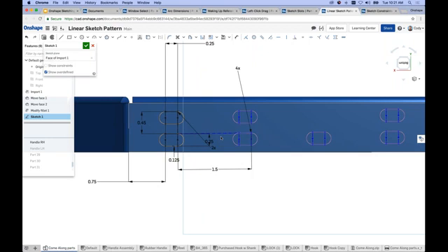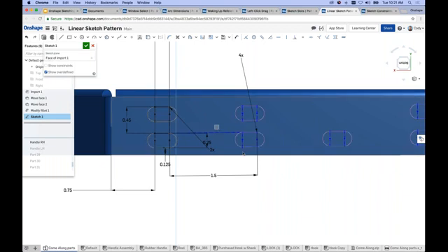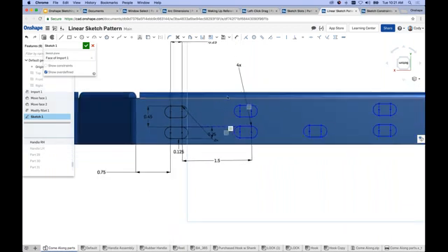The important thing I would stress is you can constrain this geometry in ways that you would typically do at the sketch level. So for instance, let's say that I wanted these slot profiles to be aligned with an edge of my part. Instead of these being constrained horizontal or vertical, I could select this line, another edge of my part, and make those parallel. And that would ensure that my pattern is parallel with an edge of my part. So again, you can get creative with these. I would place them initially, get them close to what you're looking for, and then go in and edit these, constrain these in a way that makes sense to you.